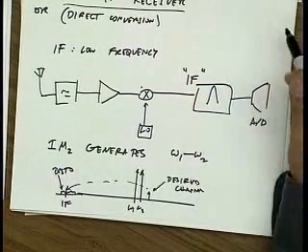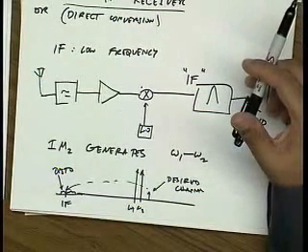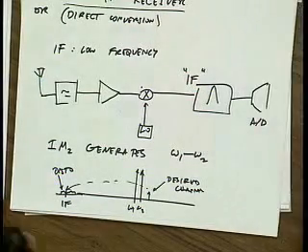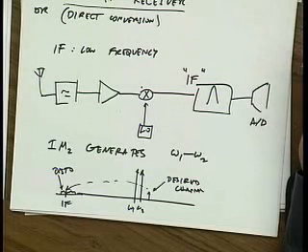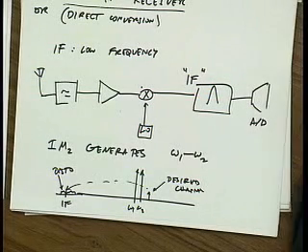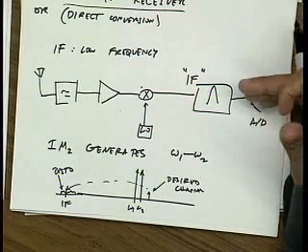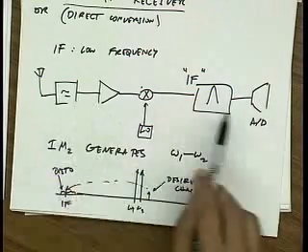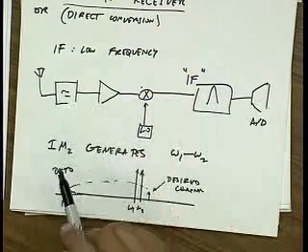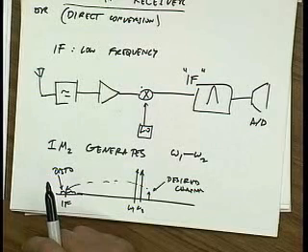Now remember last lecture, what did we say about odd order functions? Kevin? On polynomials, yeah. What was the nice thing about odd order functions? They don't generate DC. They don't generate any even order distortion terms, right? So if there's no even order distortion, we wouldn't generate any intermodulation. So in an ideal world, if we made all these signals differential, we wouldn't have to worry about IM2. Is that true? Why not?